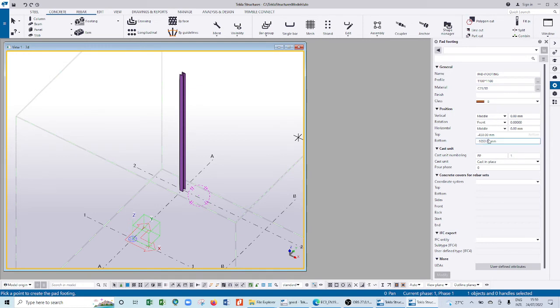After that, you go here. What is your top level of that footing? If you're going to do it, remember what we said, the footing starts from some level of 300 now. So you realize the start point is 1 meter, the footing is 300, so in total is 1.4. But down in foundation, so meaning we shall use negative 1,300 to be our top of that footing.